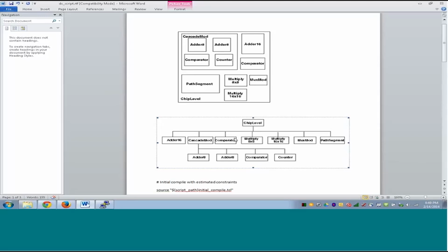We do not use characterize and write script, because for it to work, the complete design data must be present. Although in the second pass all these blocks are set as don't touch at the chip level synthesis, the complete design data is still present in the design. Now consider this problem at a chip level. At chip level, complete 100% design data is inside DC when it is doing characterize. If you try to do it for a big chip, the characterize will take a huge amount of time, and that defeats the purpose.